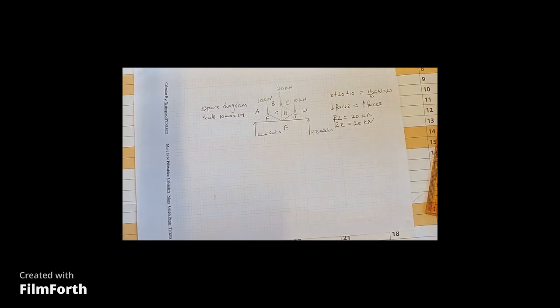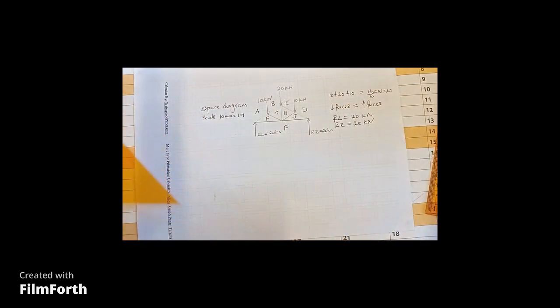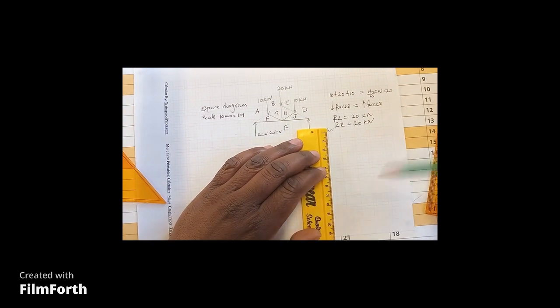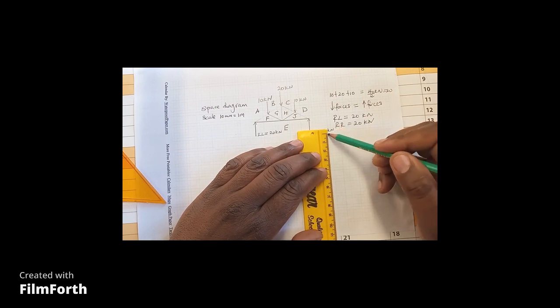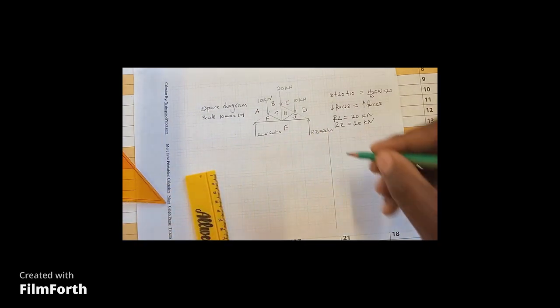Right, now we want to come to our first polygon, which is going to be the diagram that is going to help us analyze this frame. So what you do, just underneath the space diagram, just to the right hand side here, you can simply drop a vertical line, because on this line we want to represent the forces that are acting on the frame. Right, there we go. I'm going to decide on a starting point.